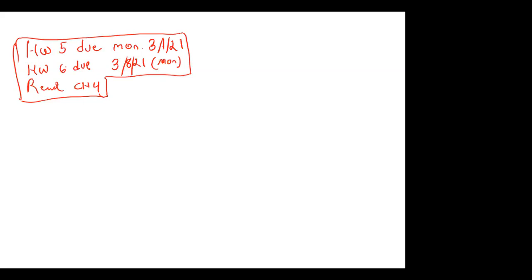16. Use K-maps to simplify the following function in sum of products form, taking advantage of the don't cares provided. Well, it turns out you always have to take advantage if they help you, and they will help you if they make your loops bigger.